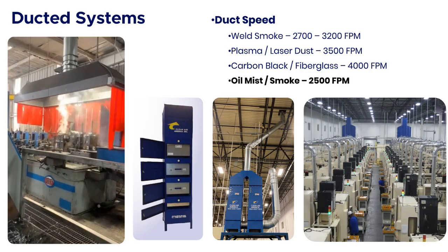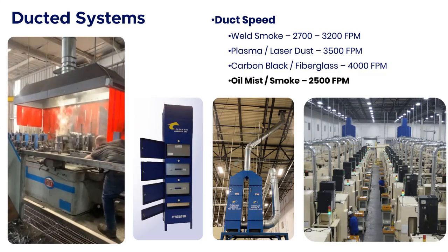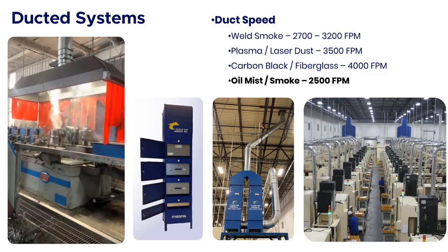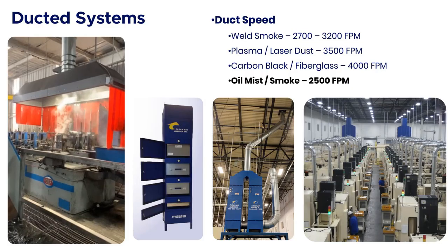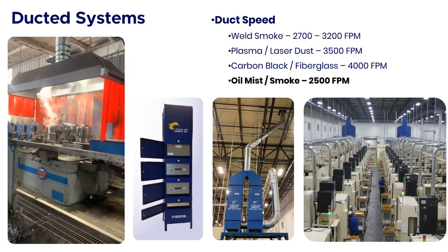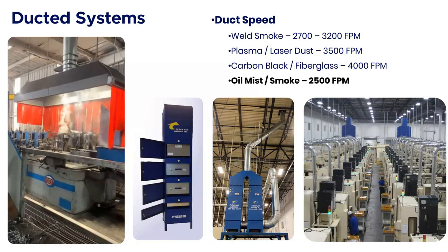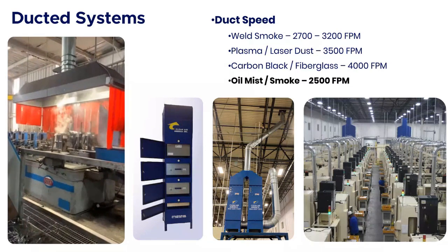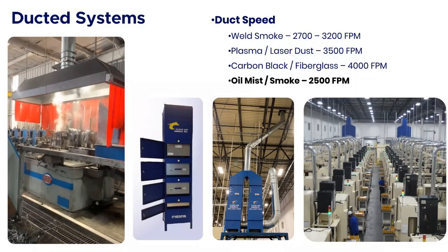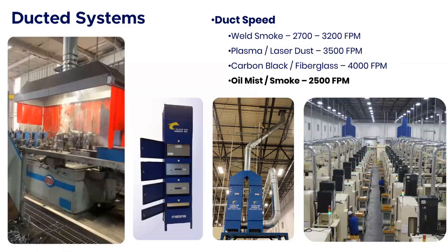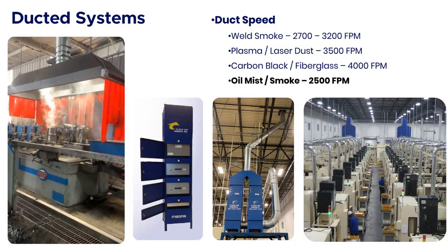They are our workhorse. You can kind of see in the third picture from the left, that's a couple of 2400s that we ganged together. In this particular application, I think I have like 10 machining centers on those two collectors, and you can see where it gangs at the bottom. Typically, we just exhaust right back out in the plant. You can see in this picture, we're actually exhausting it outside. That is the customer spec. That's what they wanted, and so that's what we gave them.